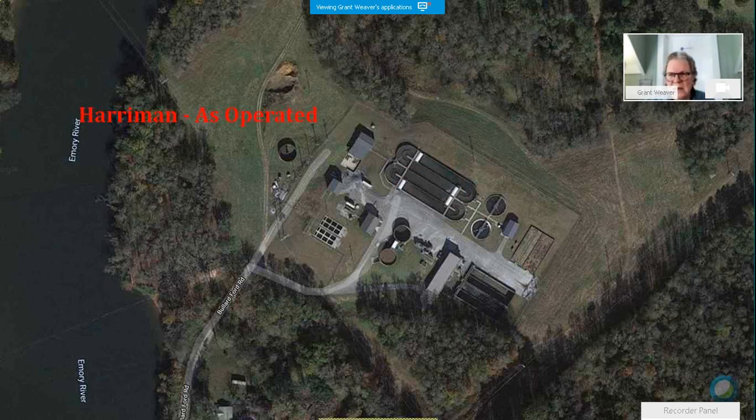And then along comes Ray, and after a few years of effort, Ray now is running 1 rotor in 1 ditch for a while, and then no rotor. And then the other rotor in the other ditch, and then no. So we've gone from 4 running all the time to 1 of the 4 running a minority of the time. Huge electrical savings, right? The biggest electrical use in most treatment plants is aeration, and they've cut the aeration by more than 75% in Harriman. There used to be 4 running all the time, now we're running with less than 1 on average.